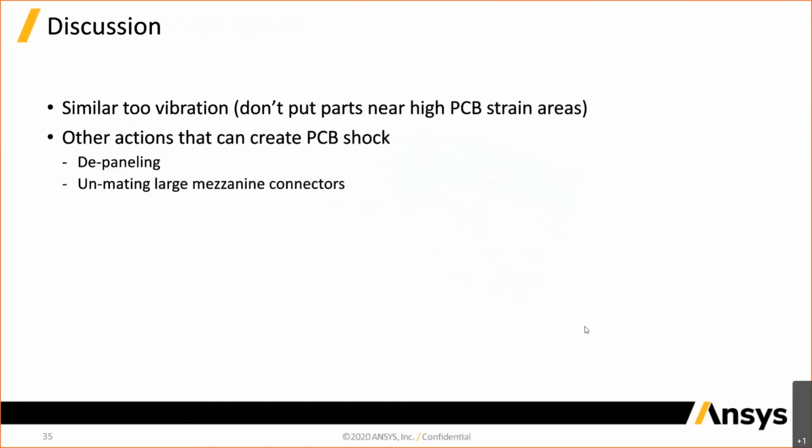It's pretty much the same guidelines for shock. Just be careful where you put your parts. You've got to consider other potential inputs for shock. It's not just drop. There's the assembly. There's the unmating and mating of large connectors. We saw that in the past where they were failing. The boards were getting damaged, and we didn't know why.